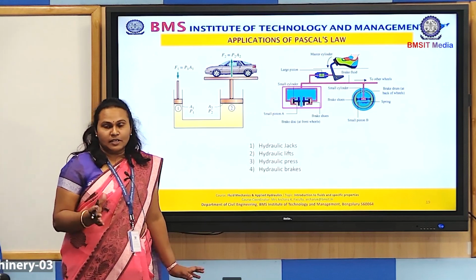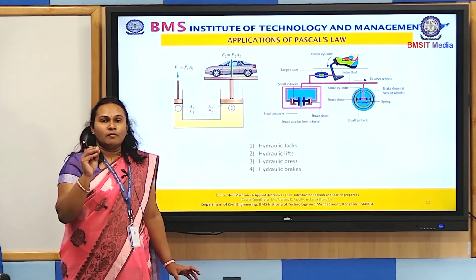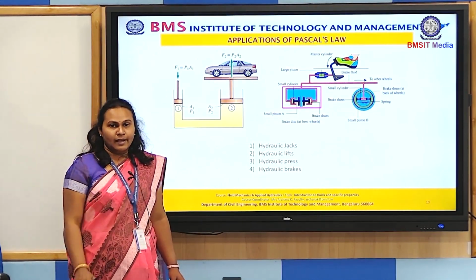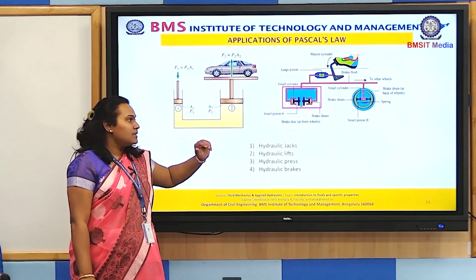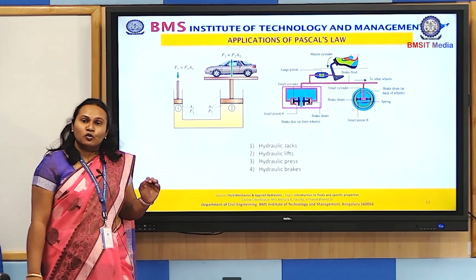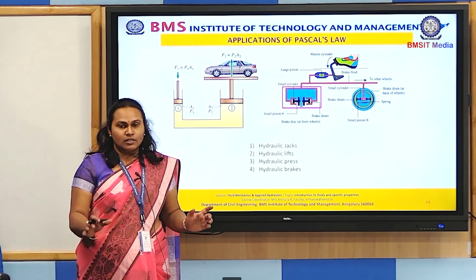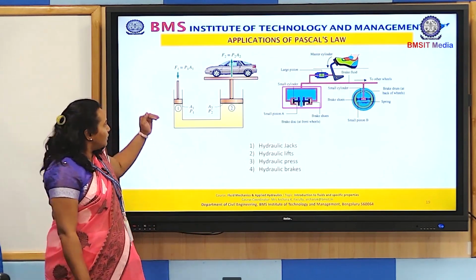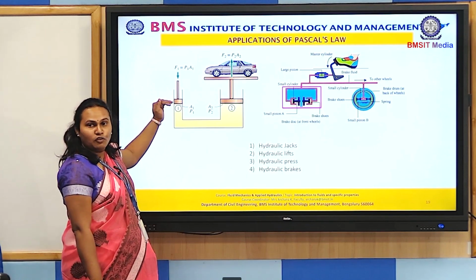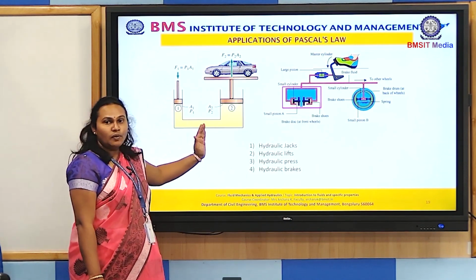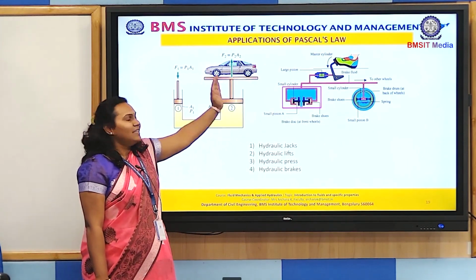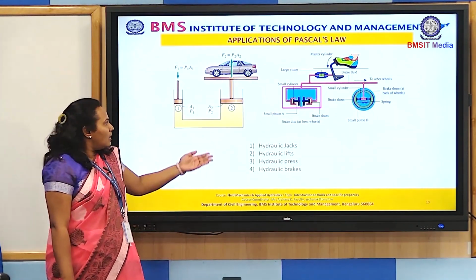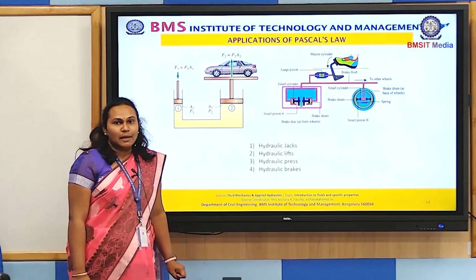If it were not, say if the fluid pressure is increasing only in the x direction, then this won't be lifted, or if it is only in the y direction, this won't be lifted. It is only because the pressure intensity in all three directions is equal that the force you're applying is uniformly distributed on the fluid, and the fluid pressure is going to be common across all three axes, and then it is going to lift the weight that comes on the ram.